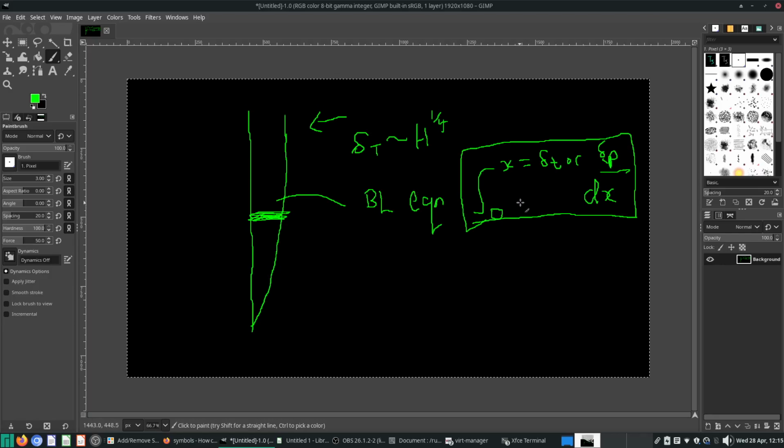What do you do once you integrate all your equations? You substitute an assumed velocity profile, and cross your fingers and hope for the best. So with your laminar hydrodynamic boundary layer in forced convection, what you do is you assume a cubic velocity profile.